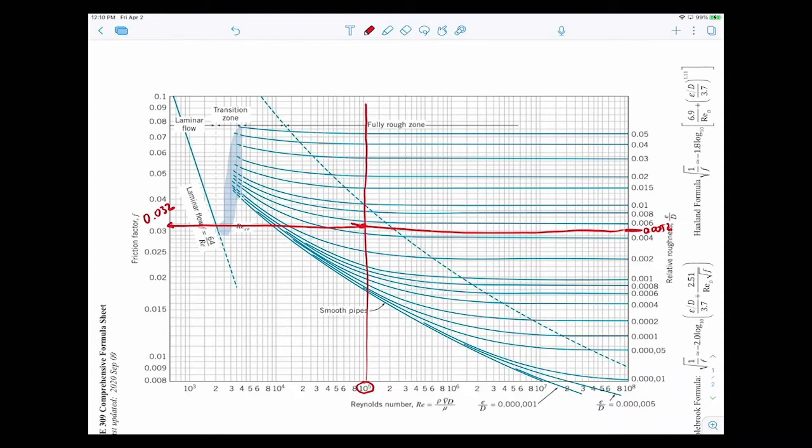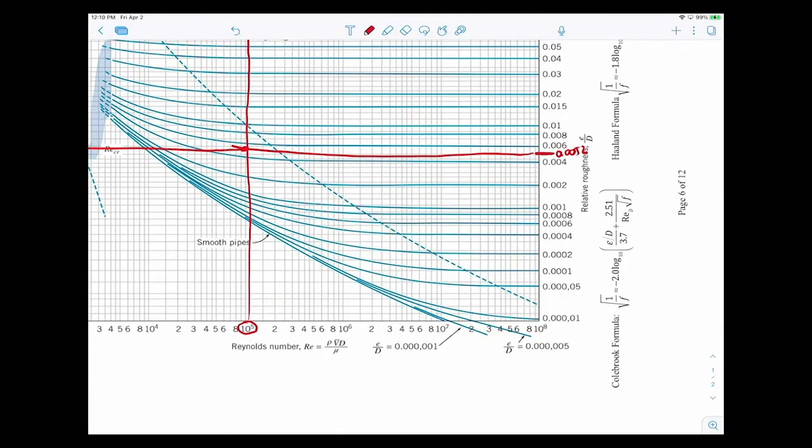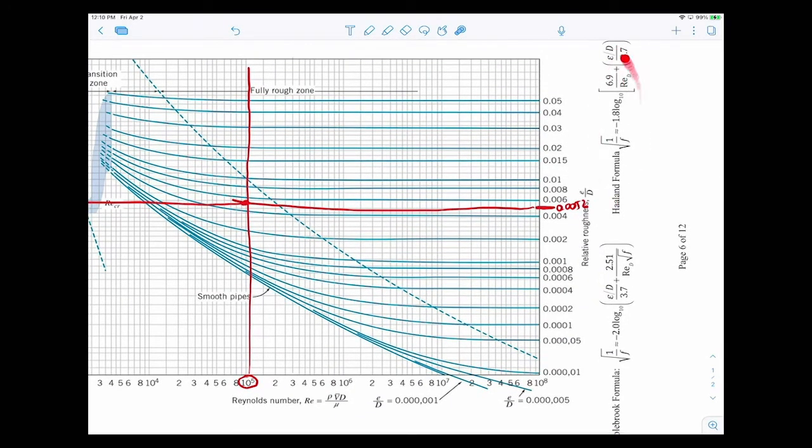Okay, so now we have our friction factor. And by the way, just make sure you know how to use the Moody plot because it'll be given on a formula sheet, right? And you'll need to use it when you do quizzes and whatnot. But in general, like doing homework, you see these formulas over here? You've got these formulas, the Haaland formula, I'm not sure I'm saying it right, and then this Colebrook formula. This is an alternate way to get those friction factors. Those are just curve fits to the Moody plot data. So that's why they look so ugly. You know, they have all these weird exponents and stuff like that. It's because it's just a curve fit to the data, and the people just fiddled with it until it really worked well.